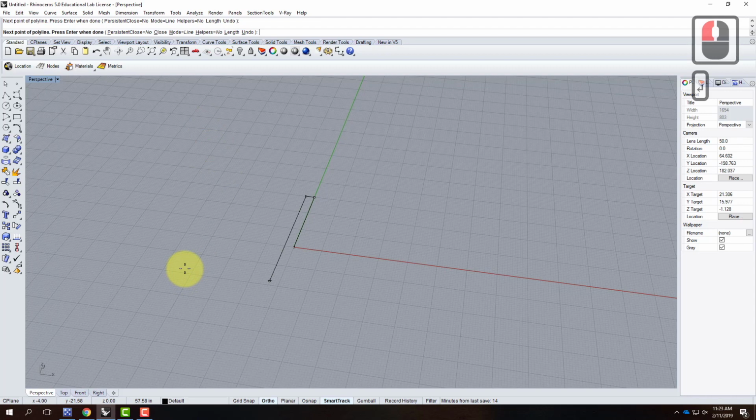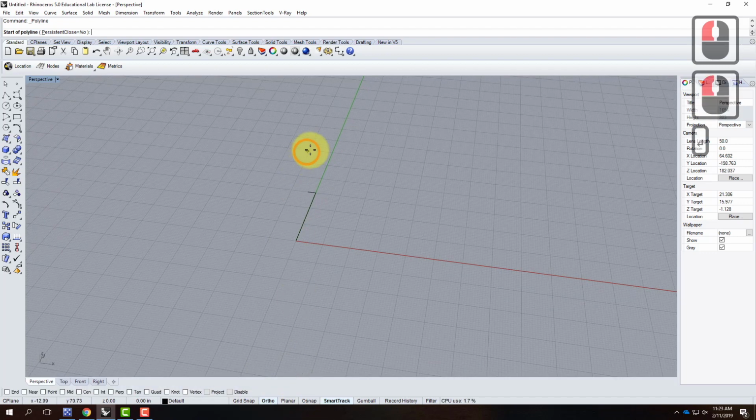Now the next piece is 36 inches down and 2 inches over. And so this is one of those challenging moments where if you really understand relative and absolute coordinates, you can come in and use that to your advantage without having to move on. If I didn't understand the difference, I'd have to finish my line. I'd have to draw a little guide that was maybe, let me turn on object snap here, with end, mid, and perpendicular.